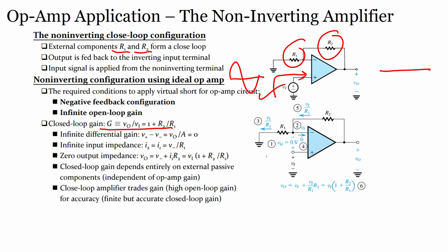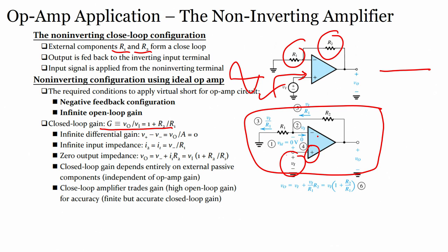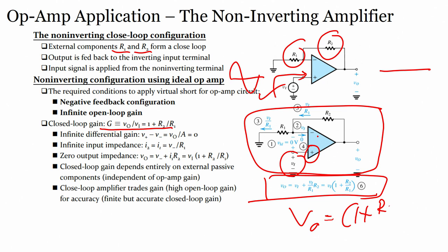So, if you see this particular circuit, what we see? We see that the input is given to the non-inverting terminal, and if you calculate the current, then V1 by R1 is flowing here, V1 by R1 towards this side, and the differential voltage is 0 volt. We have grounded this terminal, and now we are applying voltage at the non-inverting terminal. Therefore, the output that we have seen in the theory class will be nothing but VO equals 1 plus RF by R1 into V in. This is what we have seen in the class. The same thing is here.